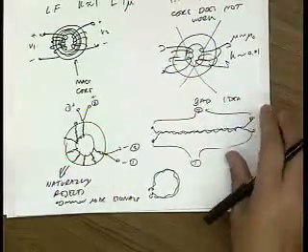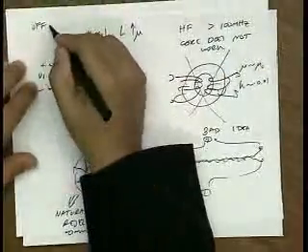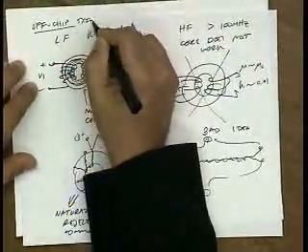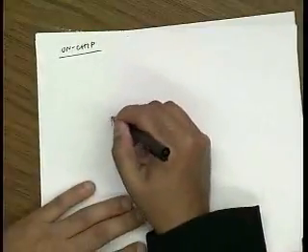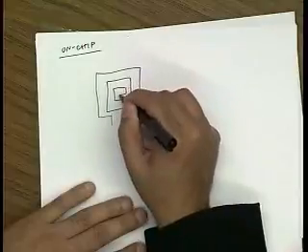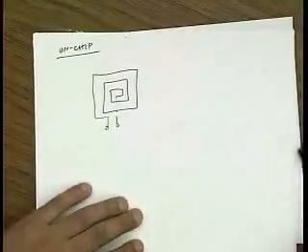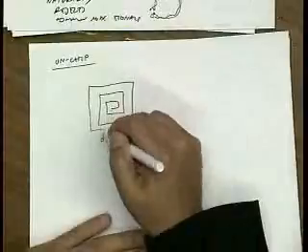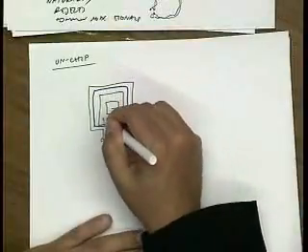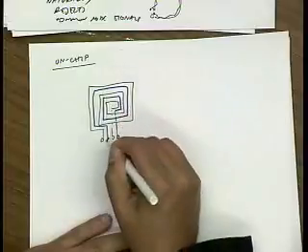Yeah, in CMOS technology, these are basically off-chip transformers, right? The way you build transformers on chip is very different. First of all, they're air core inductors. They actually use silicon or silicon dioxide, but these are non-magnetic materials, so effectively they're air core materials. And so the way you build an inductor on chip would be you would just use a spiral inductor like this, right? So this is an inductor. One way to build a transformer is very much like this. I just wind a secondary around it. So this is a transformer.